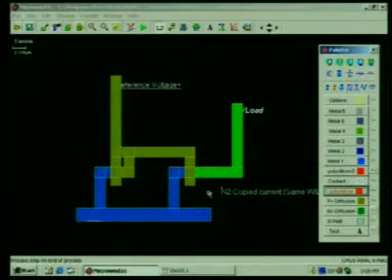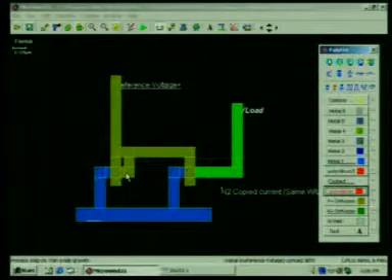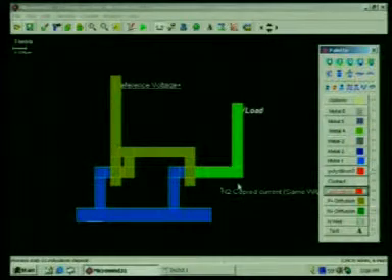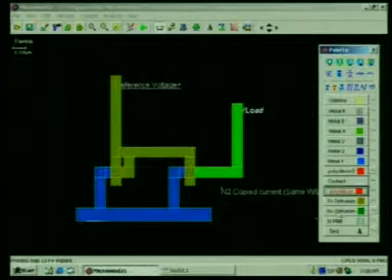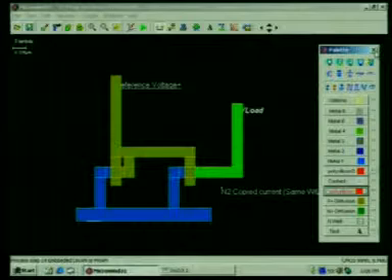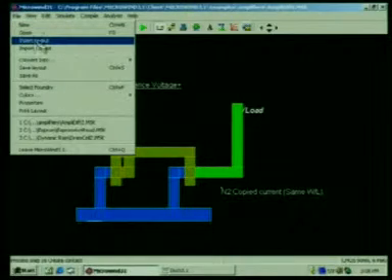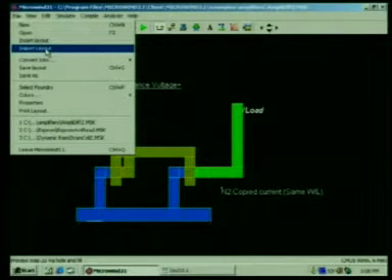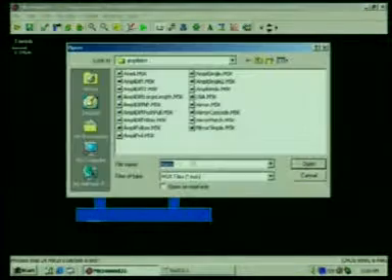Suppose he wants to divide that. So, he has to maintain the width of this one half compared to this one. So, the flexibility with this current mirror is that suppose you want to multiply the current or divide the current. So, this will be a very useful method for layout kind of designing. So, I have explained the principle of differential amplifier, why we are using current mirrors, and now I will take some other examples.